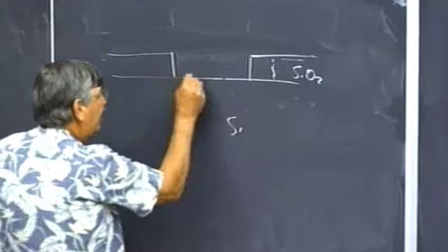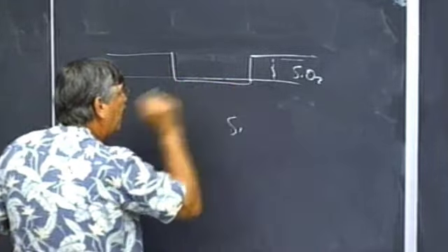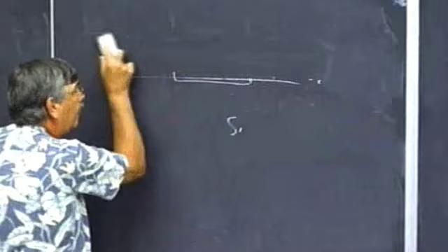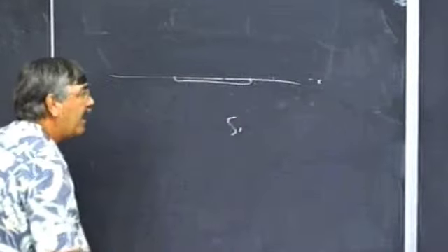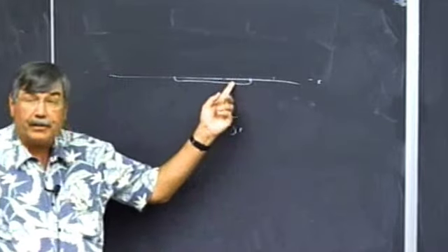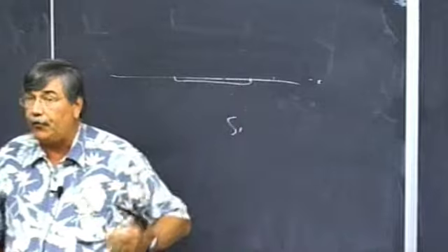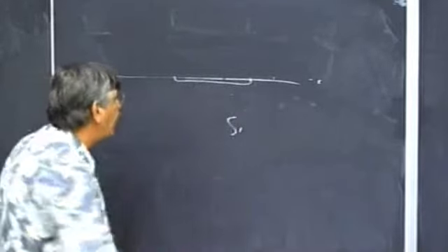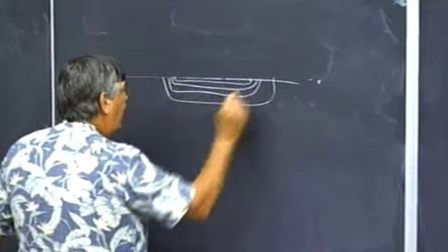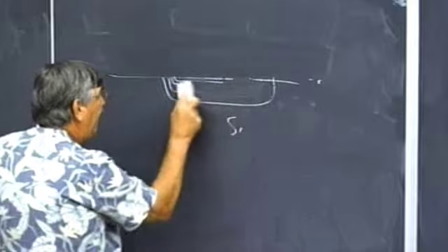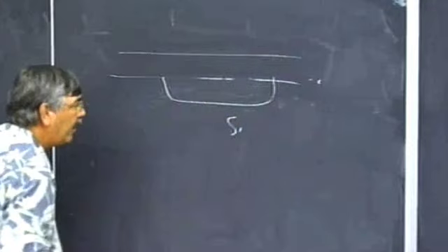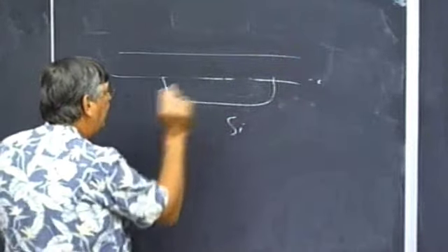And we can put a bunch of impurities at a very thin layer, controlling depth below the surface. We can either leave the silicon dioxide or usually we'll grow some more at some point. And then we take the entire silicon wafer and we put it into an oven at high temperatures, and the impurities, dopant atoms, acceptors or donors or whatever, diffuse down into the surface. So the hotter it is and the longer we leave it, the deeper they will go. And so we have then impurities that have diffused to a predictable depth in a particular location. Usually there's silicon dioxide capping everything whenever anything happens because it's hard to avoid.